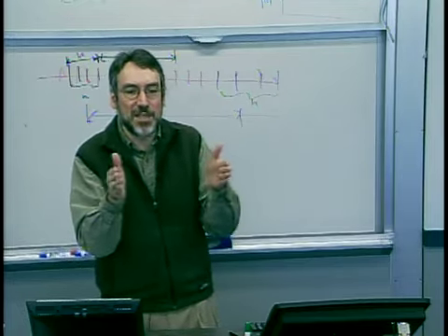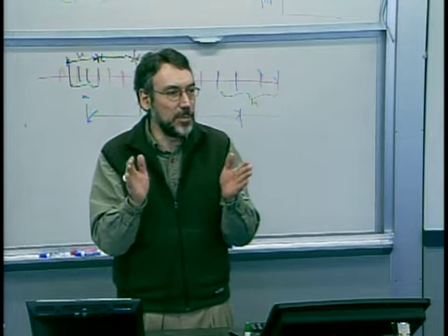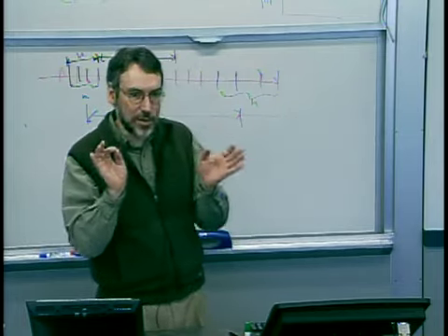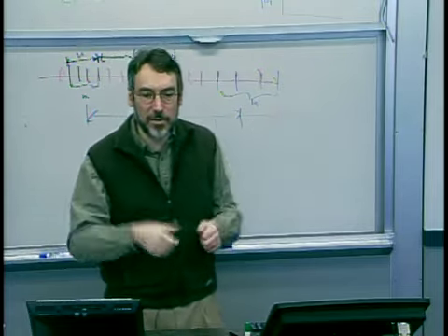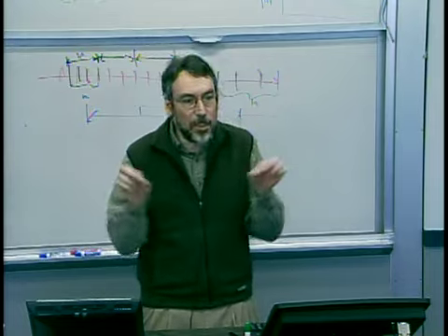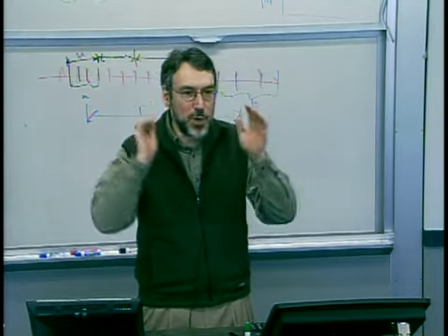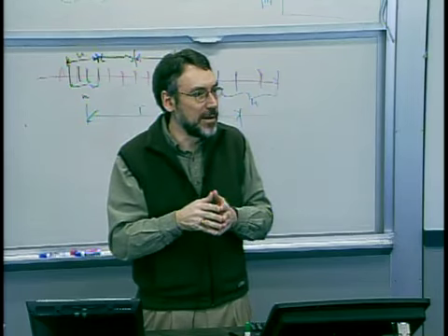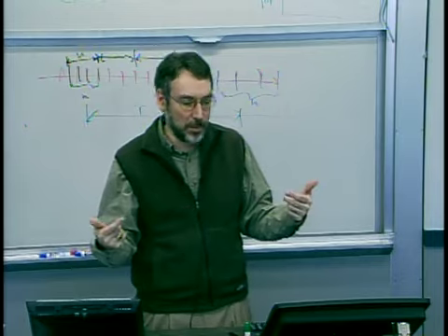If I tightened up my spec limits, if you just even know just a CP and CPK, you can back out, because that's all in terms of normalized standard deviations, probabilities associated with the number of parts that are not going to conform to those specifications. So if I purely tell you CP and CPK, you know probabilities, fractions of non-conforming parts.